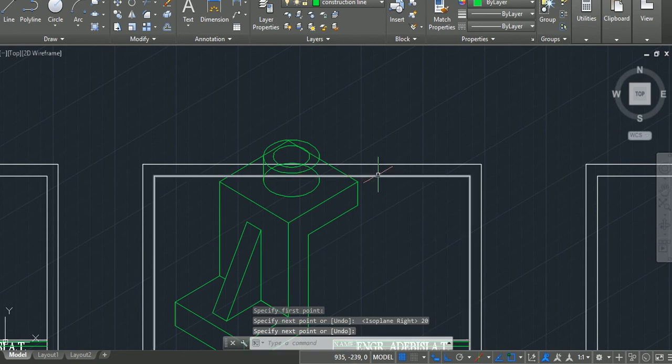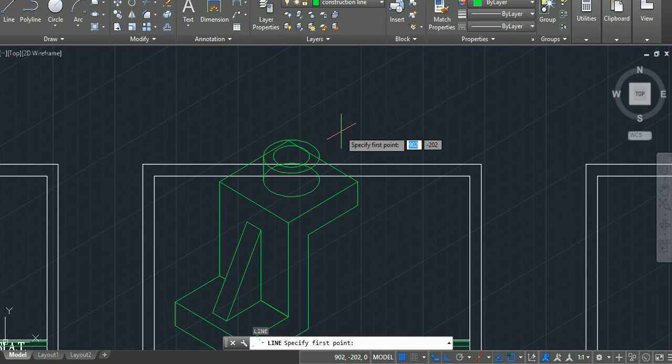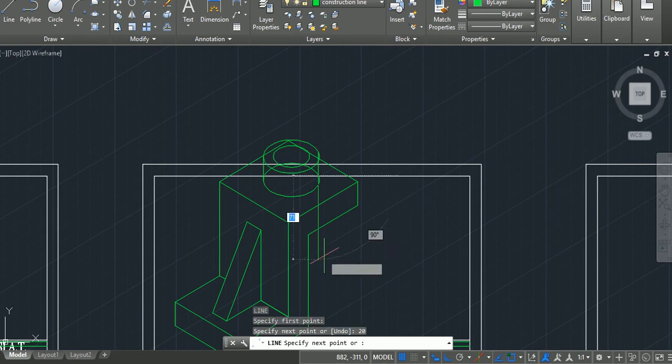You know, when you draw a circle and you start from the center line, the circle has 4 junctions, or we can say 4 quadrants. And what I've done here is to simply locate 2 quadrants from here and use them to plot what I did. Now I will zoom in and trim the trimmables.